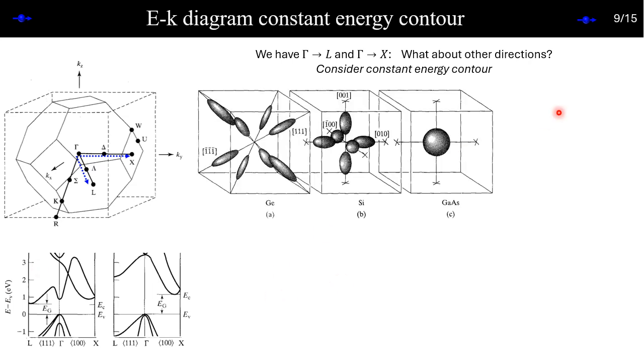This is what it will look like. These are the energy contours, meaning we consider constant energy. Here we will consider constant energy near the band extrema, because whatever is happening very high above, we don't care, as you can have constant energy surfaces at different positions. Think of it this way for gallium arsenide, which was a direct band gap.